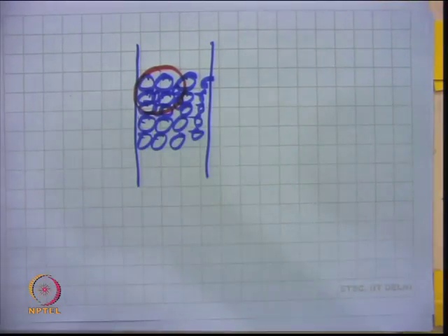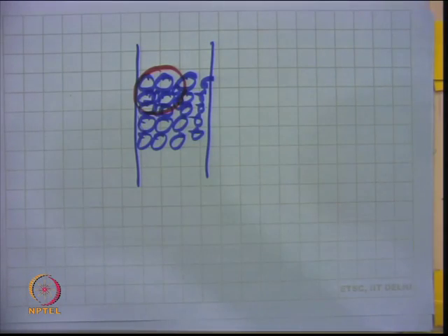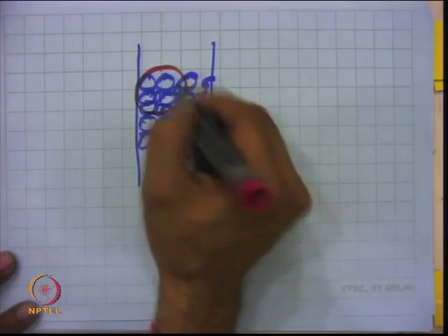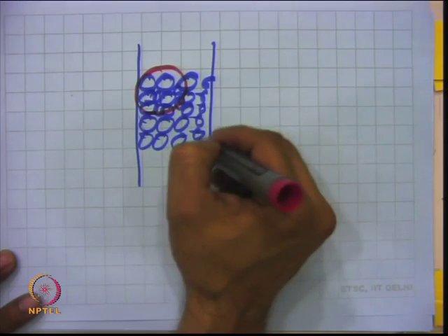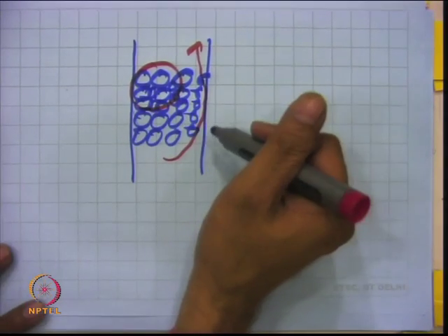Suppose you have a very fine powder unlike this, where the voidage is very poor, and you make it tapped compact and try to pass the gas, you will feel that the gas will not pass through that. So, the contact becomes poorer and poorer, or the gas will try to pass through channels like this. So, this is a bad kind of design.